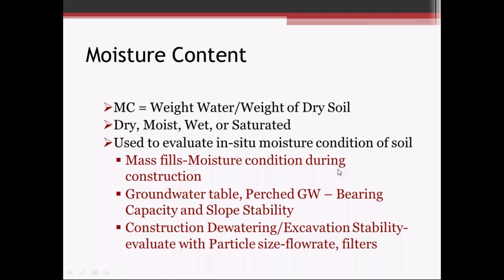If the soils are on the wet side of optimum, then the soils have to be dried out, which would take more time to place the fill, depending on how much above optimum, as well as the time of year the fill is placed. With the weather conditions outside right now in the fall, very little soil drying would occur this time of year.